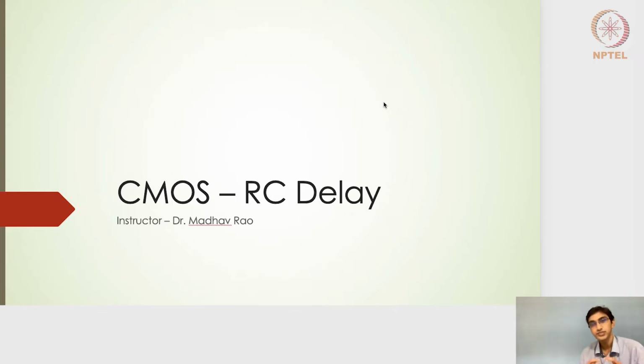In a sense, if you use the transistor itself, in our case an inverter, a very primitive digital circuit, what are the delay or performance values, and what kind of estimation methods do we have to employ so as to reach those delay parameters? To be very specific, it will be the propagation delay parameters. And once we calculate that, how do we then model it appropriately as an RC circuit? That's what we are going to learn in this lecture.